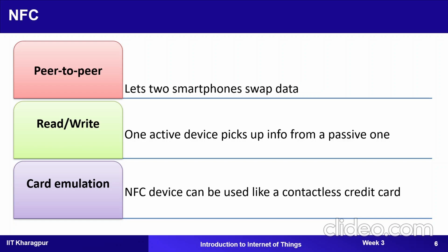A central network controller device sets up and manages the Z-Wave network. So basically there is one controller device which is going to manage the whole network. Each logical Z-Wave network has one home ID and multiple node IDs. The network ID length is 4 bytes. However, the node ID length is 1 byte. It uses a source routed network mesh topology using one primary controller.